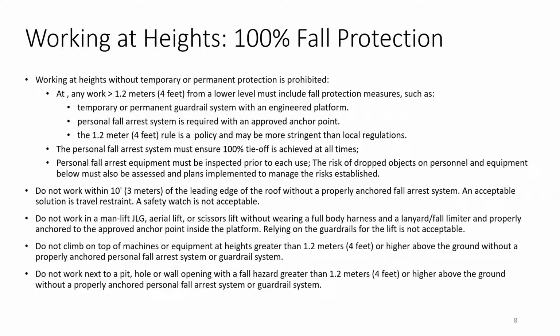Do not work in a man lift, JLG, aerial lift, or scissors lift without wearing a full body harness and a lanyard or fall limiter, properly anchored to the approved anchor points inside that platform. Relying on the guardrails for the lifts is not acceptable.